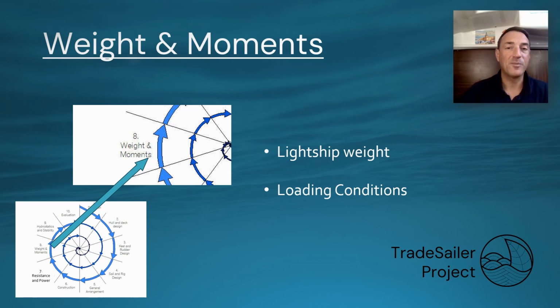We're in the 8th step of the first iteration, so we're almost there. Yes, we're going to look at the lightship weight, which is the weight of just the ship, the functional weight. And we're going to look at the loading conditions. So basically we're going to add to the lightship weight the dead weights such as cargo and fuel.